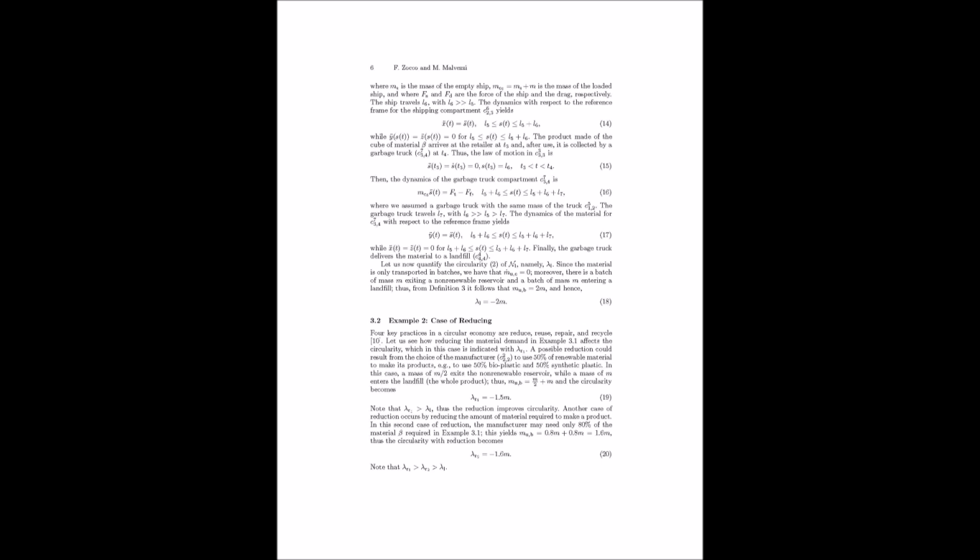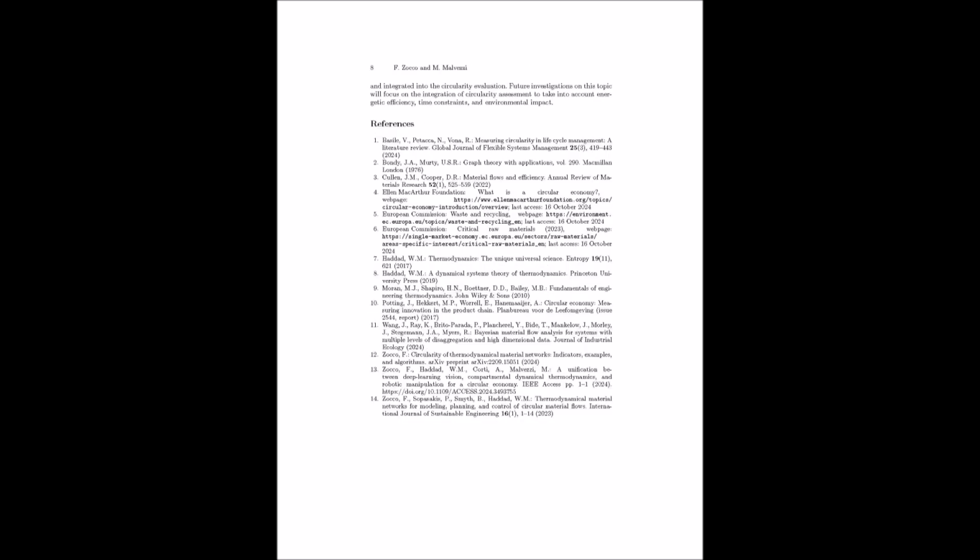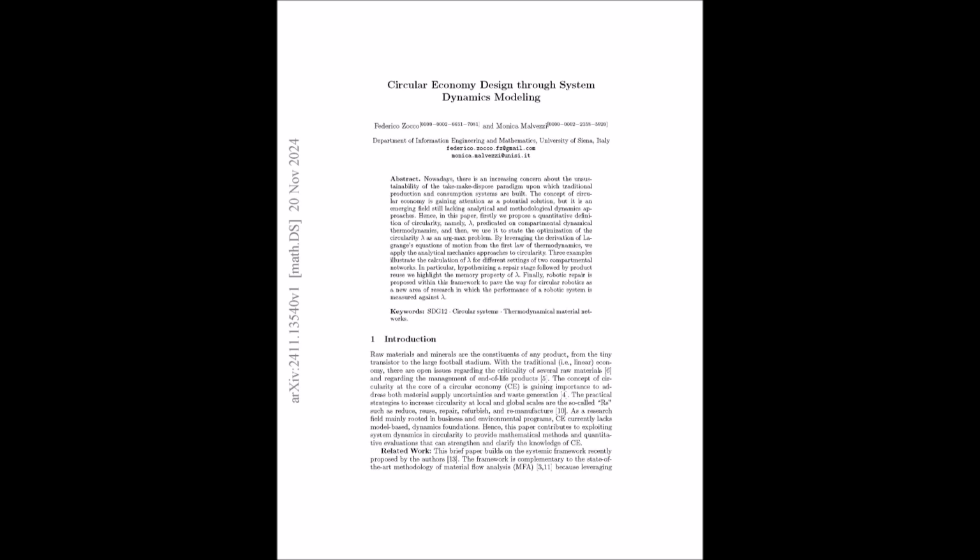Right. Then equation 7 defines the potential energy, M. They're being very specific, even defining the height, that z, as a function of the distance the truck travels on a sloped path. Getting fancy. And then equation 8 uses the good old Lagrangian equation of motion to figure out the truck's acceleration. It considers all the forces at play: the truck's engine force, friction, even the component of gravity acting on that slope.